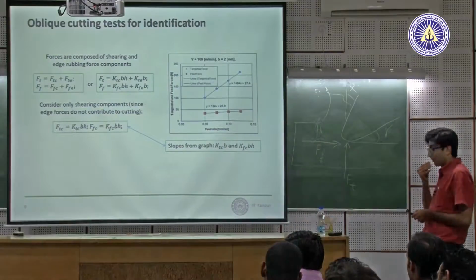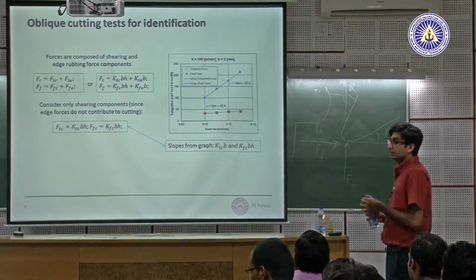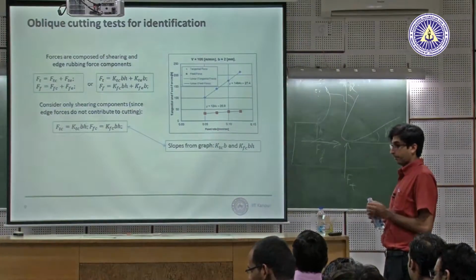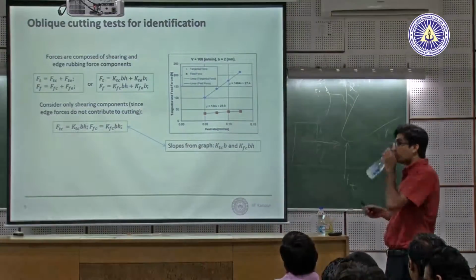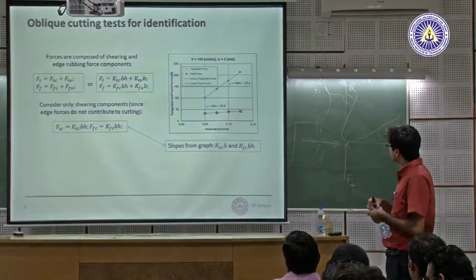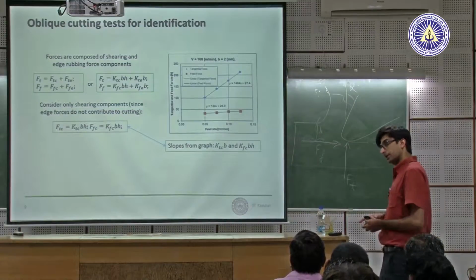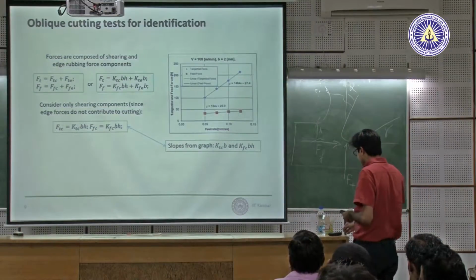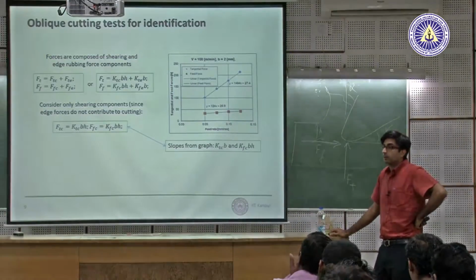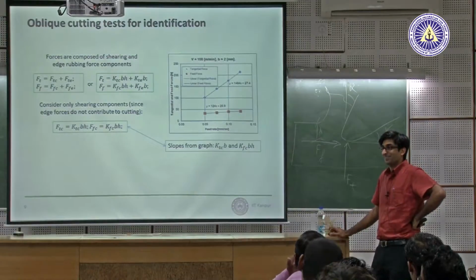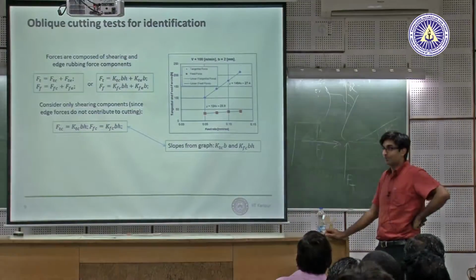I will conduct this, for example, if I do a machining of MS, the speed range will be 70 to 120 or 70 to 150. During my testing, maybe I will assume 70. Here the only parameter variation is the feed. Maybe at the customer place, suddenly we can change the cutting speed. Yes. But the KTC or KFC value, the constant, will it be the same, or if I am varying the cutting speed, it will be different? Huh? Then I have to. So you see the sheet that we have given you, right?